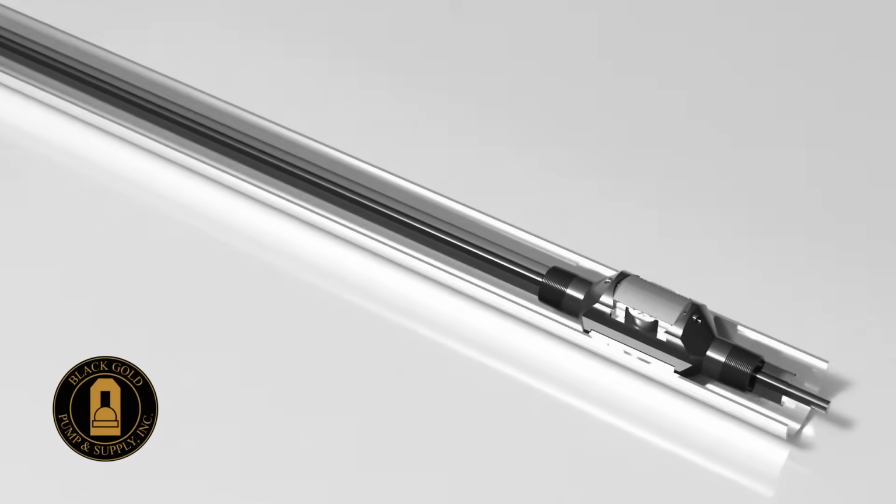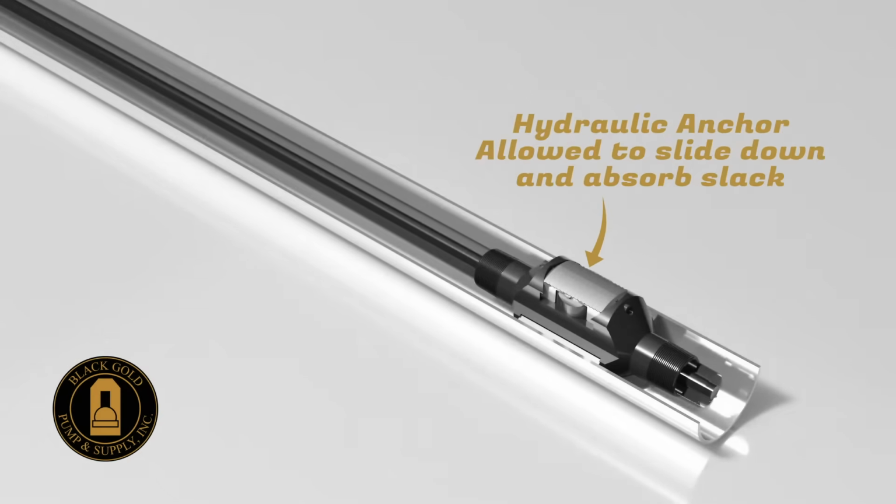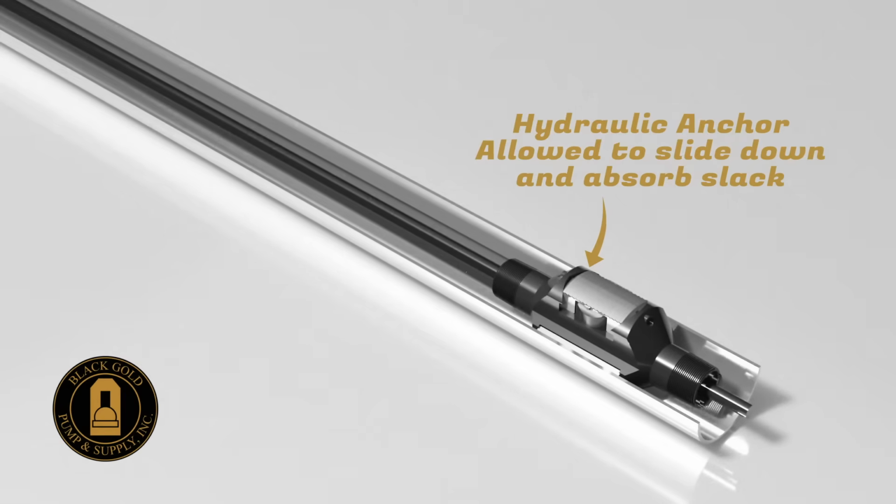Instead of pulling the slack out of the tubing like with a mechanical anchor, the hydraulic anchor allows that slack to automatically compensate downwards. Once the tubing is filled with fluid and there is a slight differential pressure between the tubing and casing, the hydraulic anchor will engage. This setting process happens automatically without any surface manipulation. No turning, stretching, or calculations required. Just run the pump or plunger in the hole and fill the tubing with water or turn the well on. That's it. Your well is now properly anchored.